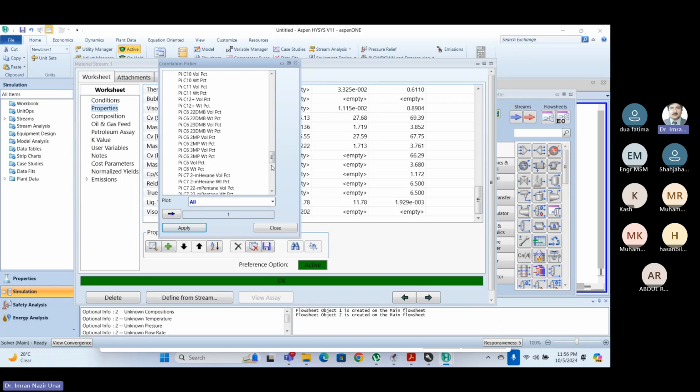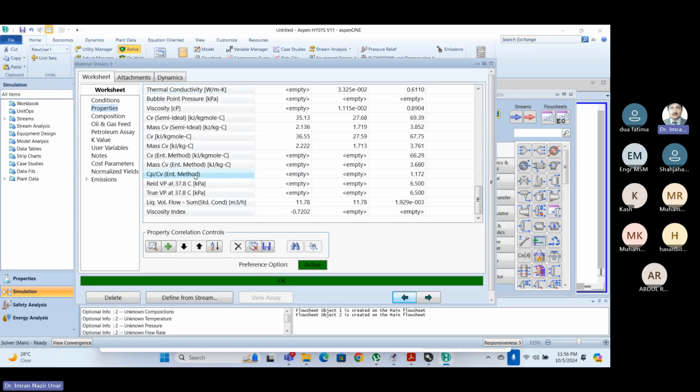If you have a gas composition, you just click and it will calculate and give you the appropriate results. For example, in petroleum or in a gas, you can calculate the HHV, HC dew point, which was not available there, and Wobbe index. So many correlations and properties can be added to this list and then they will be visible.